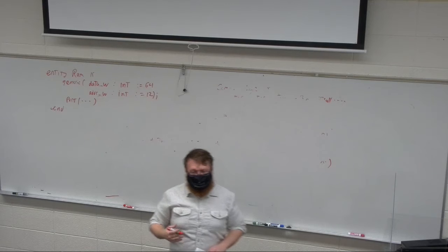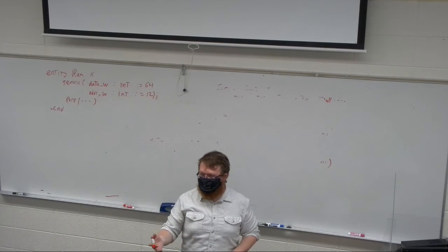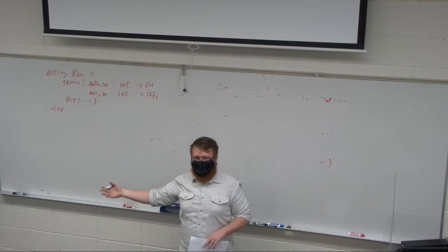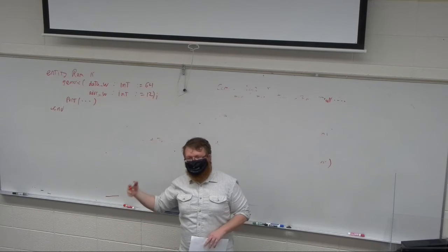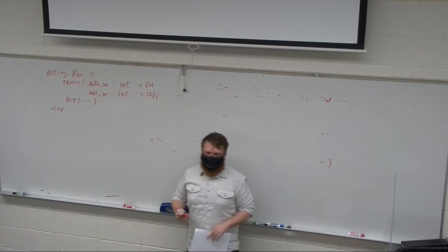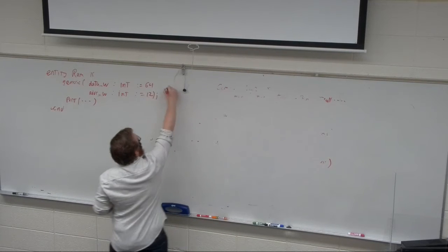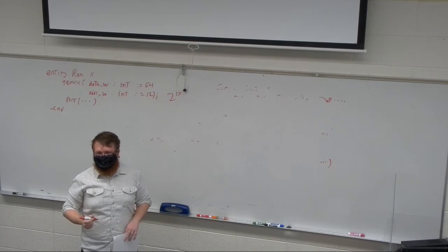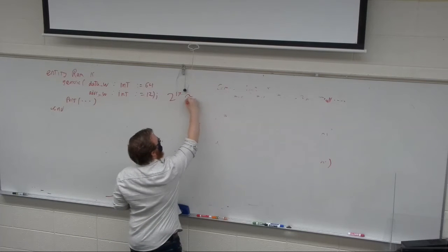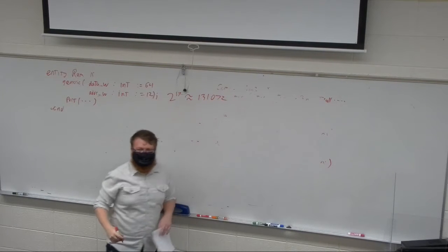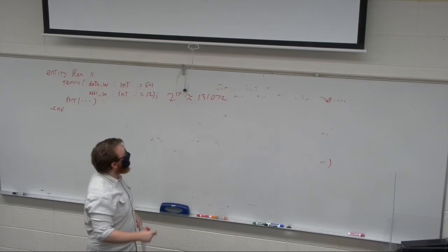You've seen something like this when we created the ROM, where we wanted to use 100,000 locations, 100,000 addresses. The ROM didn't create it with 100,000 addresses. It created it with 2 to the 17 addresses, which is 131,072 exactly.